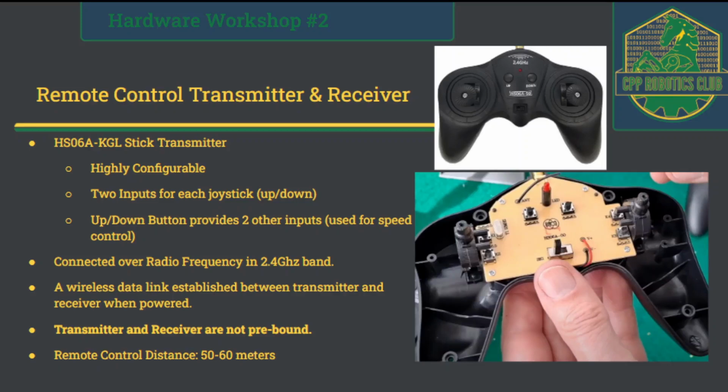If you look inside the receiver PCB, it's a very simple design. You basically have 6 different buttons and one power push switch. How it works is that when you push the joystick forward, it presses one of the buttons, and that sends a signal over to the receiver, and then one of the outputs on the channel of the receiver becomes 5 volt.